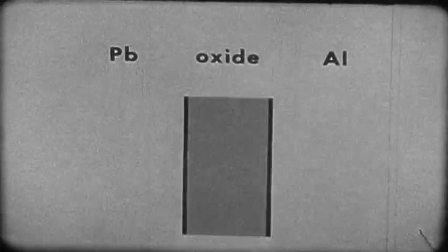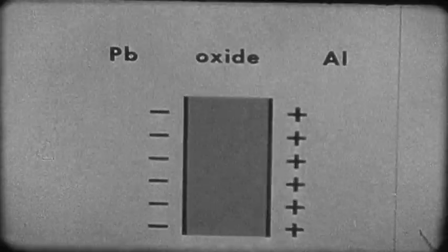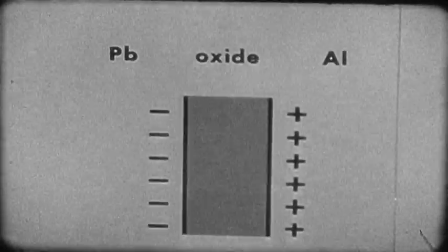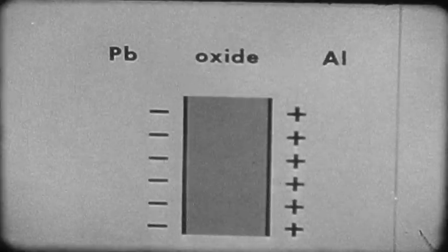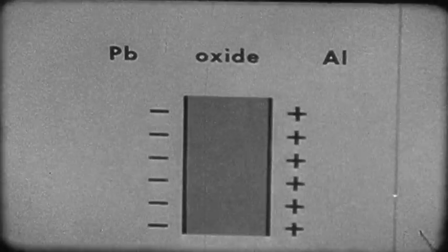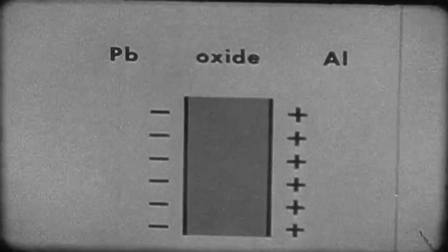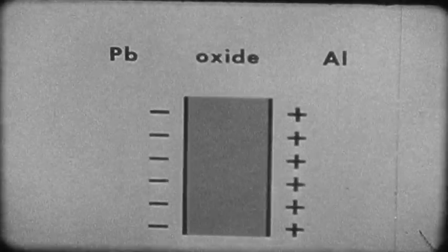The oxide of aluminum is a non-conducting substance, a dielectric. At the junction where the 2 metal films lie above each other, it separates them. We are justified in thinking of a parallel plate condenser. If we apply a voltage between the metal films, or condenser plates, we would expect, in terms of elementary classical physics, the little condenser to become charged, and that is that. Only if the voltage were high enough to produce breakdown in the dielectric should we expect an appreciable flow of current across the oxide.